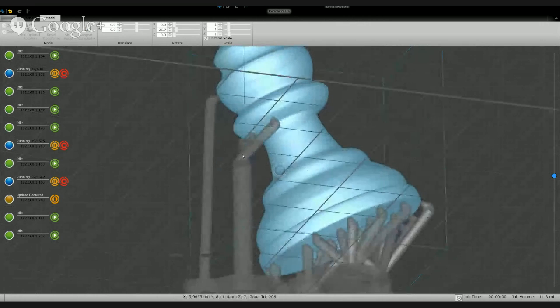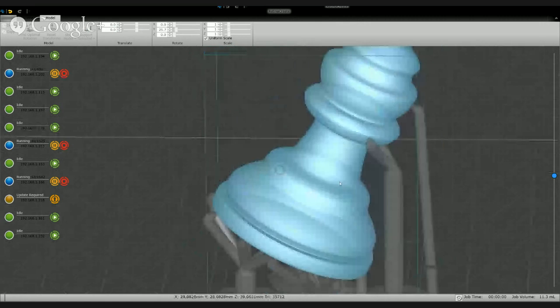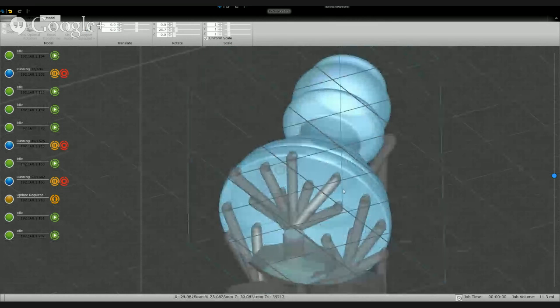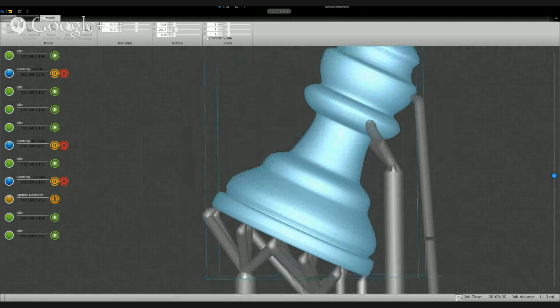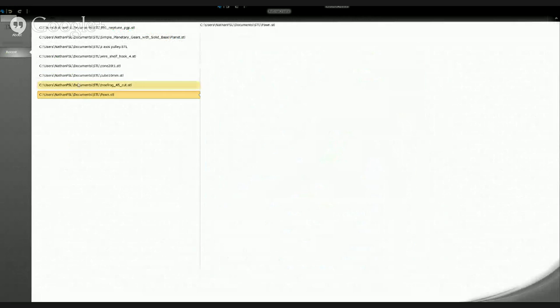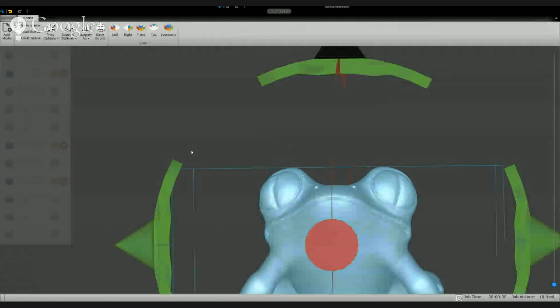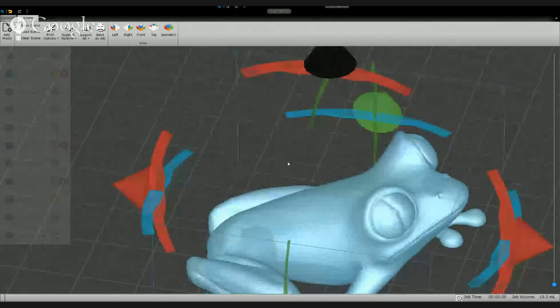So I'm excited about the trees. We've only done 2 prints with support trees so far, so it's a very new feature that's fairly untested, but it saves a lot of resin, and it seems to be just as structurally sound. So as I'm talking about these things, I hope that you get an intuitive feel for what needs to be supported with an SLA printer and what doesn't.